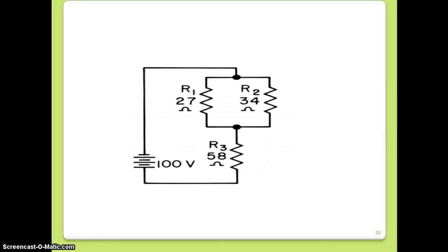Now, in a series parallel network, we often have to do more analysis, like we may have to find out many currents and many voltages. So here we can see there is a total current. Total current gets divided because there is a parallel branch, and on the other junction these branch currents again combine together to get back the original total current. So we have to now find out the total current and the branch currents. Also, there will be a voltage drop across each of these resistors, which could be different, V1, V2, V3. So we have to do the calculation of these voltages as well.